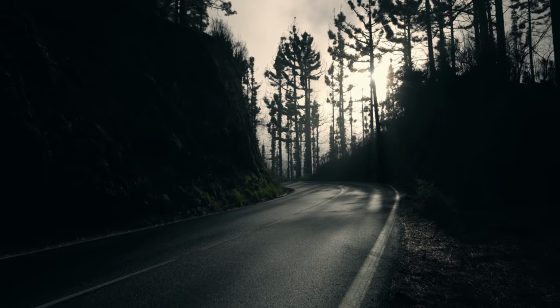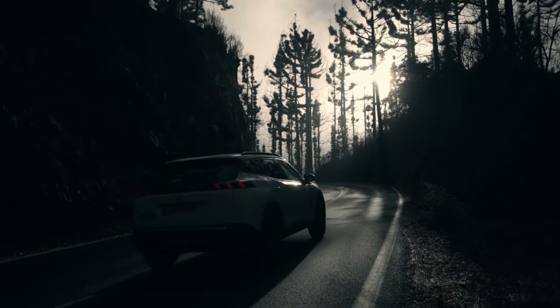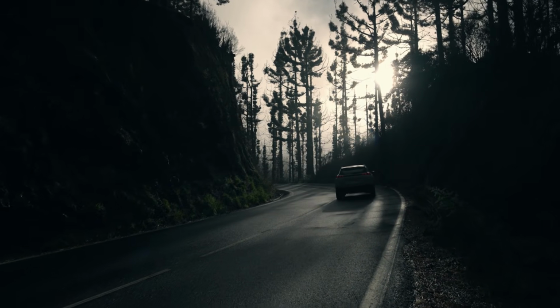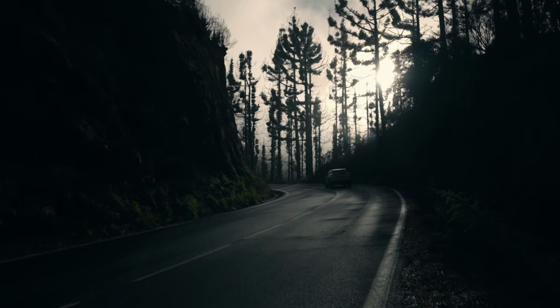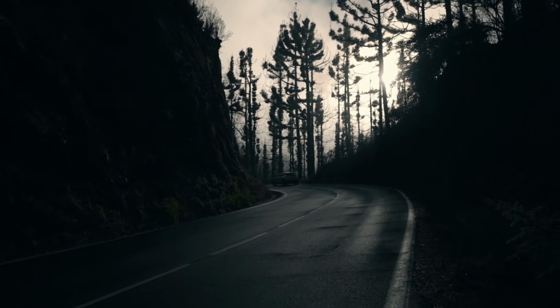The ECU requires a short relearning period of approximately 20 to 50 kilometers after the fuel trim reset to establish new baseline correction values. During this period, idle quality and fuel trim values will stabilize progressively. Full adaptation is typically complete within one full drive cycle.